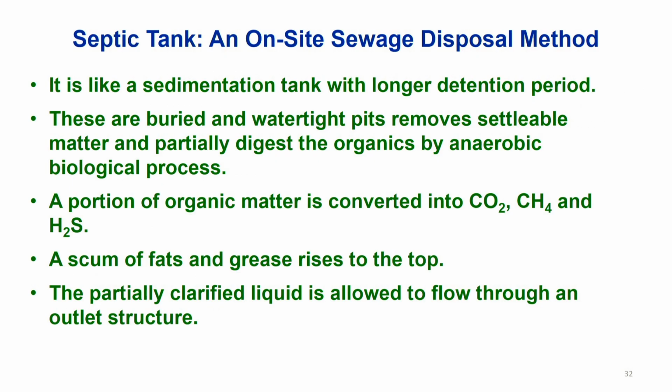Now, what is a septic tank? It is an on-site sewage disposal method. It is like a sedimentation tank with a longer detention period. These are buried, watertight pits that remove settleable matter and partially digest the organics by an anaerobic process. Basically, an anaerobic biological process takes place here, and some portion of the organic matter is converted into methane, CO2 and H2S.